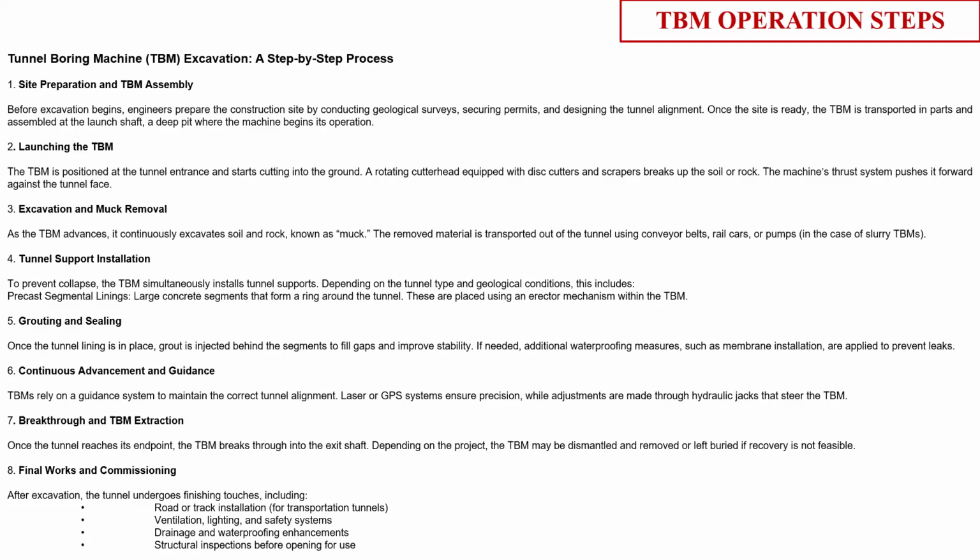It depends. It's basically a logistics operation. It's nothing to do with the design. It's mostly decided by the TBM operation team or the site execution team who are working, on how they will launch the TBM, how they will break through, and how they will extract the TBM at the intermediate point. But all these temporary structures designed for TBM assembly, launching, and retrieval are designed by the contractor, and this design is mostly vetted by the detail designer of the contractor. So this is part of the designer's work.